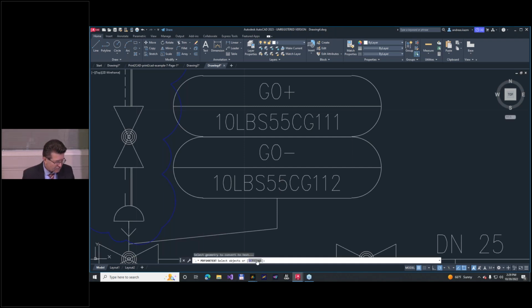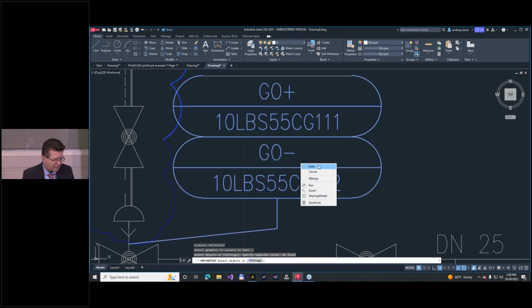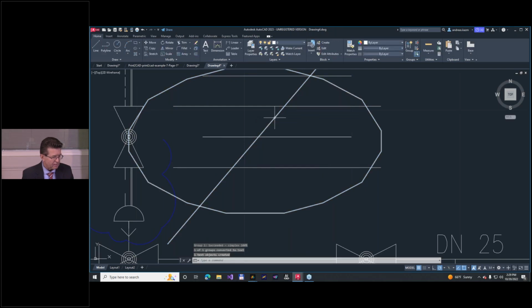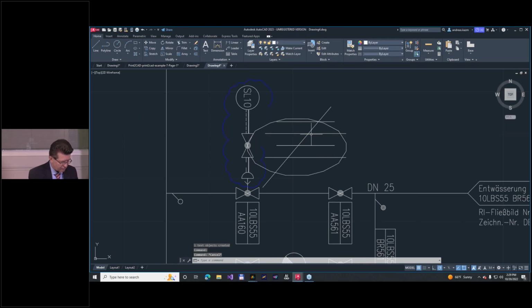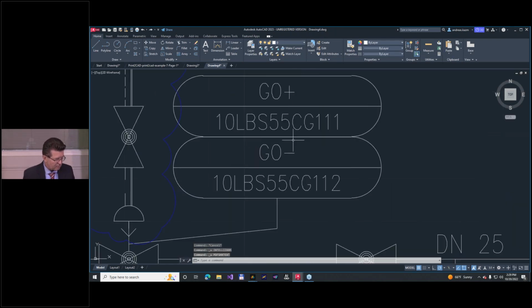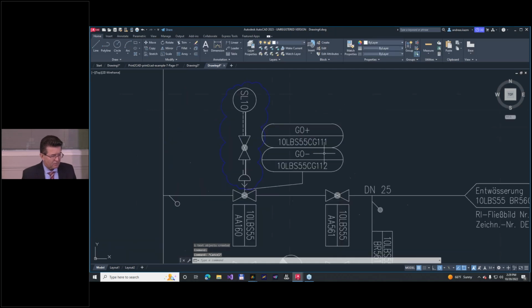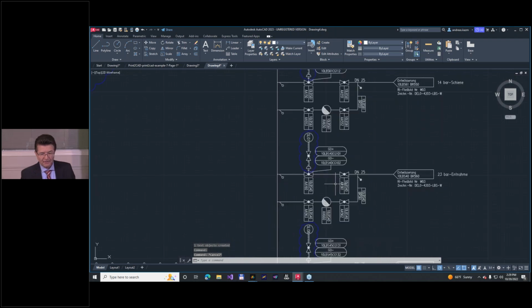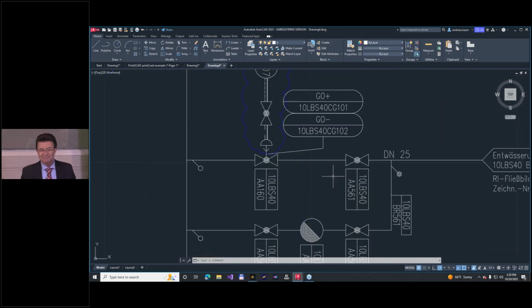But we check it here, PDF SHX text. Okay. And select object. We'll select this object here and enter. Okay, and bang. Oh my God, disaster. You can see. Okay, so let me go now here on PDF SHX text, and we try to separate it like this. Okay, enter. Close. This looks good, but what does it mean? Now we have to go through the full drawing, and every text you have to separate manually. A lot of work, and nobody is doing it.